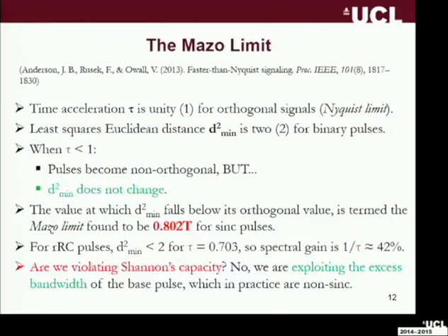And when you come to compute the bit error rate and recover the bits, when you've got all the noise, so if you think about QPSK, for example, and then with noise it becomes something like this, what you're doing is computing the distances between the soft point that you received and the ideal point, and trying to figure out what point is actually the correct one. And that's what we term Euclidean distance. And what you found is, for example, for binary pulses, the Euclidean distance is 2.